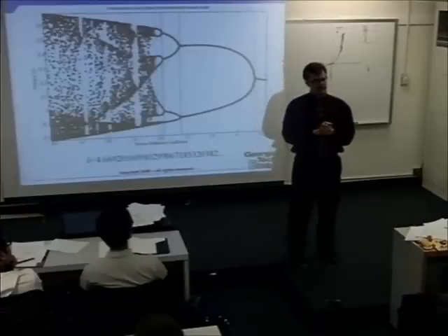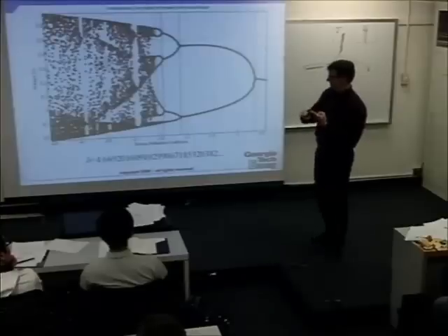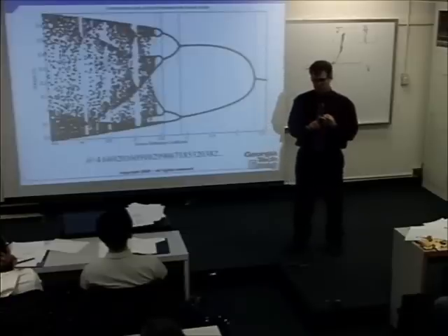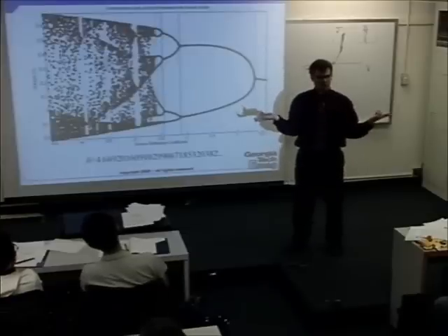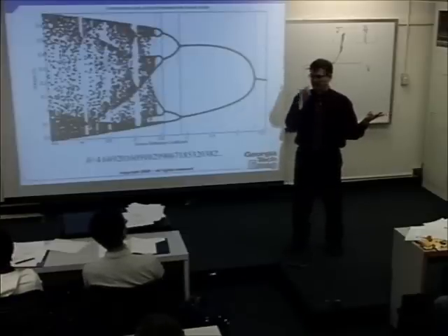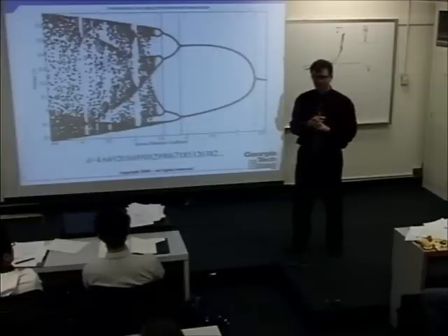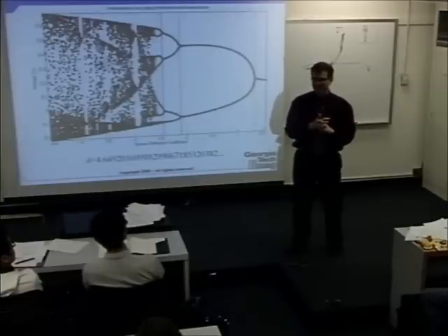We need at least a third order system to see chaos in a circuit. And yet this one, we have our nonlinear element, we got the tunnel diode, we have a source supplying some force. There are no inductors and capacitors in there. I just have a transmission line. How did I get to order 3 circuit behavior or higher? The transmission line is made of inductors and capacitors. Yeah, that's right. We smuggled them in the transmission line.